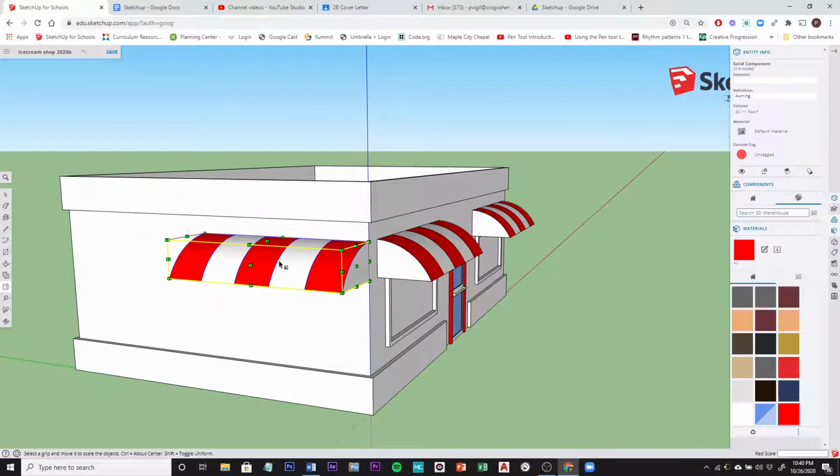If I wanted to scale the height, I would grab this little guy here. That's just adjusting the height of the object. I'm going to escape out of that. What I want to do is scale the entire thing. So I want to keep the ratio of height to width. I just want to scale the whole thing down. So that would be one of these corner options. That's going to scale both the height and the width. And if you scroll over it, the screen tip says uniform scale about opposite points.